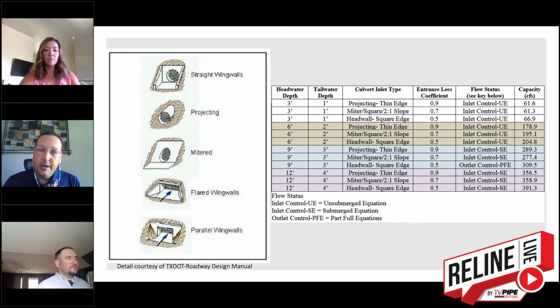And it is a complex issue. It's one that I wish I knew better. I try to have discussions with hydraulic engineers to make sure I'm not speaking out of ignorance because of my level of understanding versus theirs. But when you are putting a smaller pipe in, you're typically going to force this pipe into inlet control, meaning they're only going to flow as much water as that inlet's going to allow. So the enhancement device, the HydroBell, is trying to improve that.